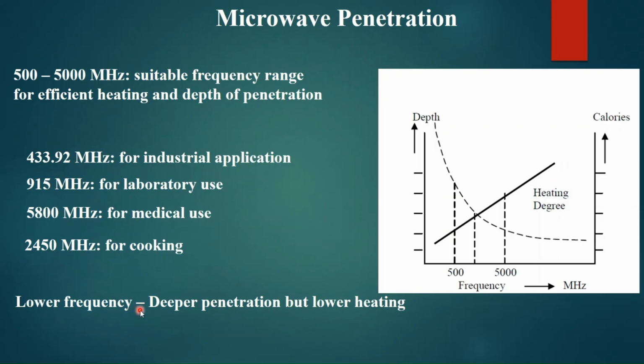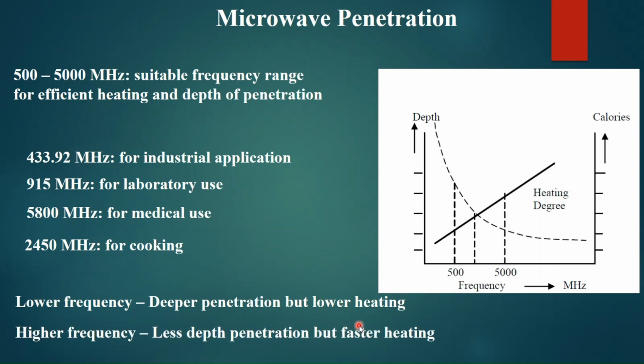Lower the frequency, deeper is the penetration. But however, there will be lower heating. Higher the frequency, lesser the depth of penetration. Thus, it is having faster heating.